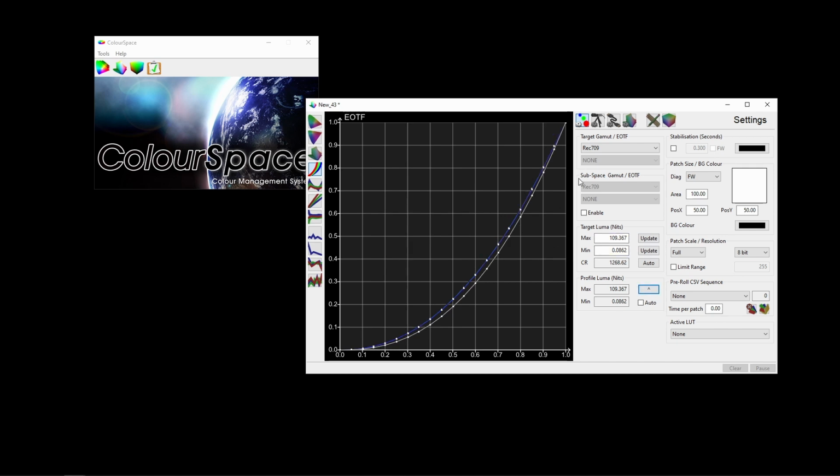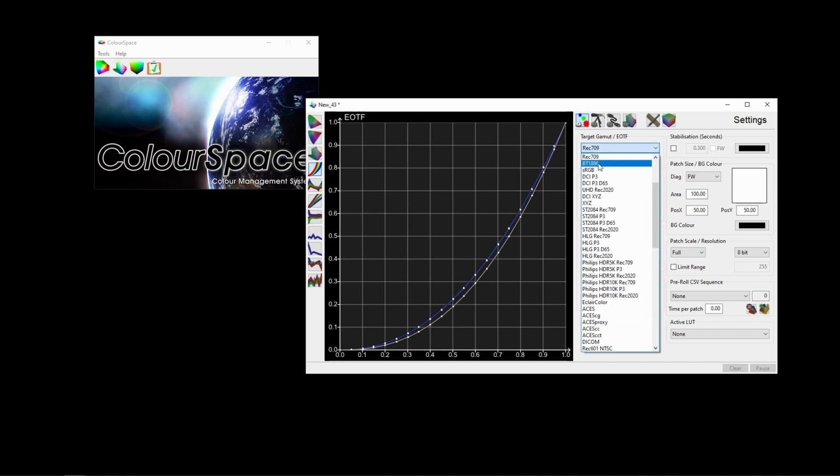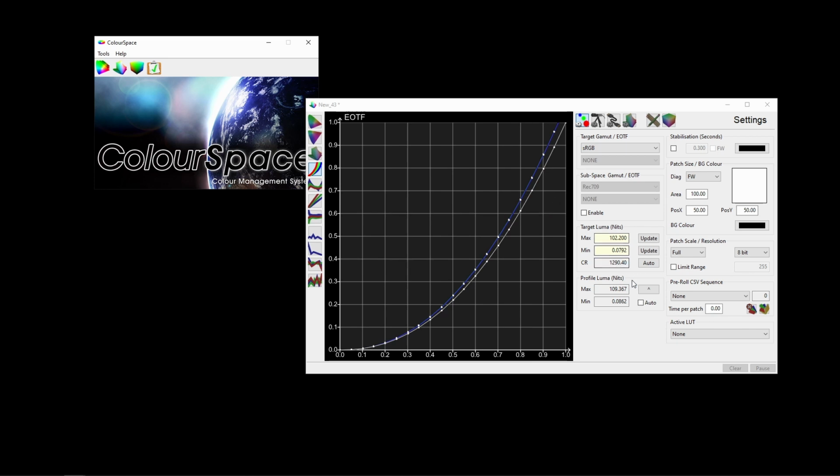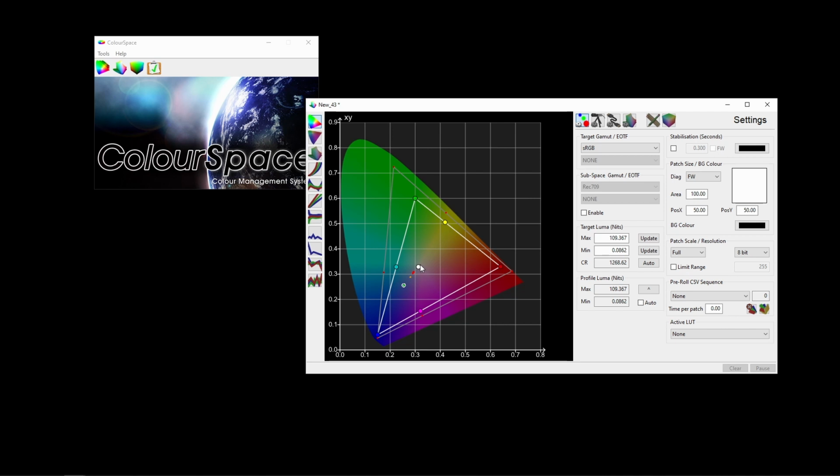And so you'll see this gamma difference here because we're on Rec 709, but the gamma on the native panel is basically a 2.2. So when we select the 2.2, which is sRGB, and we redo our luminance levels again, you'll notice it's basically a 2.2 gamma all the way across here, a little kink there. You'll notice here on our balance that the monitor is showing very, very blue, but the red and the green, they track almost identically. So that's basically the difference between our white point here for D65 and our point here.